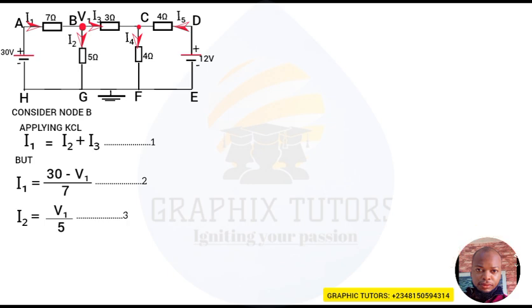Now we'll go to I3. I3 is in between V1 and V2. Let me term this point C here as my V2. So node C, I will term it as my V2. So my I3 will be the voltage from where the I3 is coming from, which is V1, minus the voltage to where the I3 is going to, that is V2, all over the resistance in between the two of them, which is 3. So my I3 is equal to V1 minus V2 over 3. That will be my equation 4.